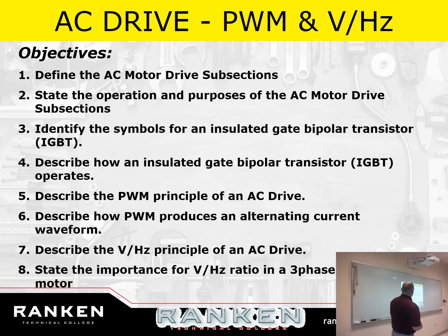I just did that. And we're going to describe the volts over Hertz principle. I did that a tiny bit yesterday. I introduced that, talking about the volts over Hertz principle, right? If we start messing with the frequency, we start messing with the reactance that's going on inside that motor. We start messing with the CEMF, the counter electromotive force, that resistance that's in that motor from the magnetic field.